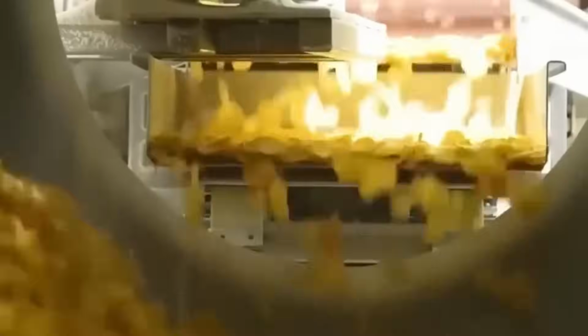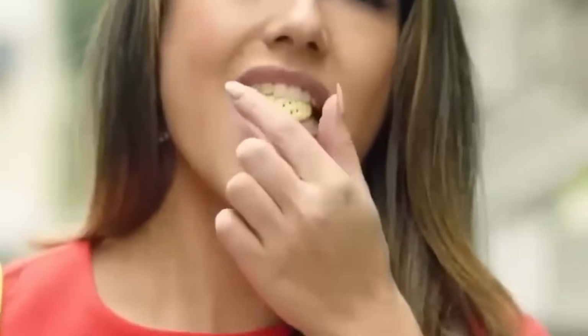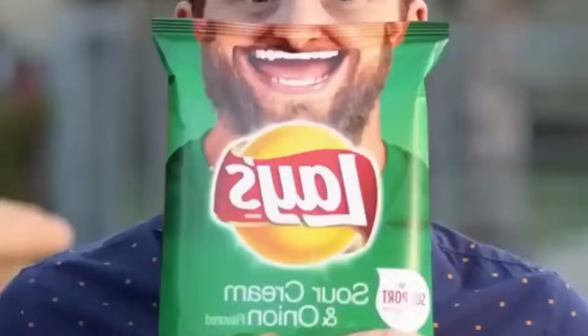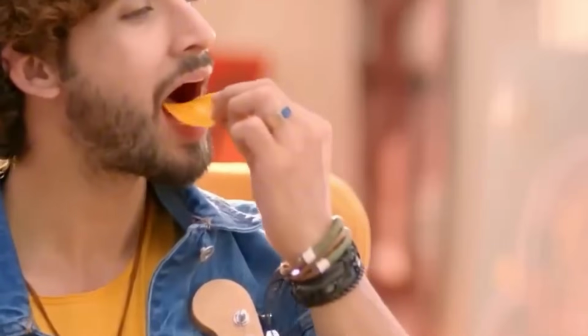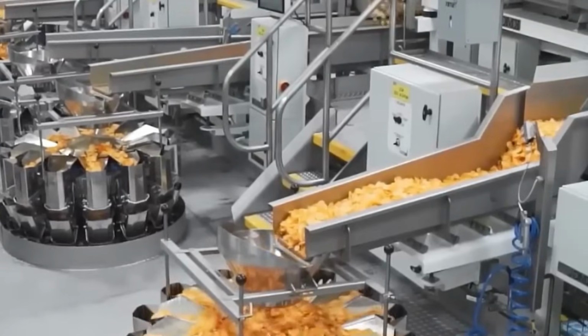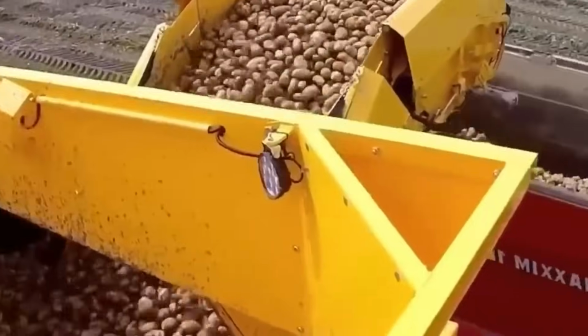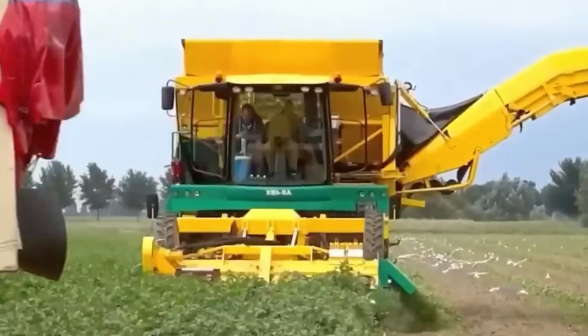From the seasoning drum, chips are transferred via vibrating or belt conveyors to the packaging area. Along the way, they pass through optical inspection systems that detect burnt or misshaped chips using near-infrared cameras and remove them using targeted compressed air pulses. Chips then fall into the radial combination weigher, which consists of multiple buckets that each dispense a known quantity. A computer selects the optimal combination of buckets to match the target fill weight with high accuracy, typically within plus or minus 0.1 grams. Portioned chips are released into the forming tube of a vertical form fill seal machine.